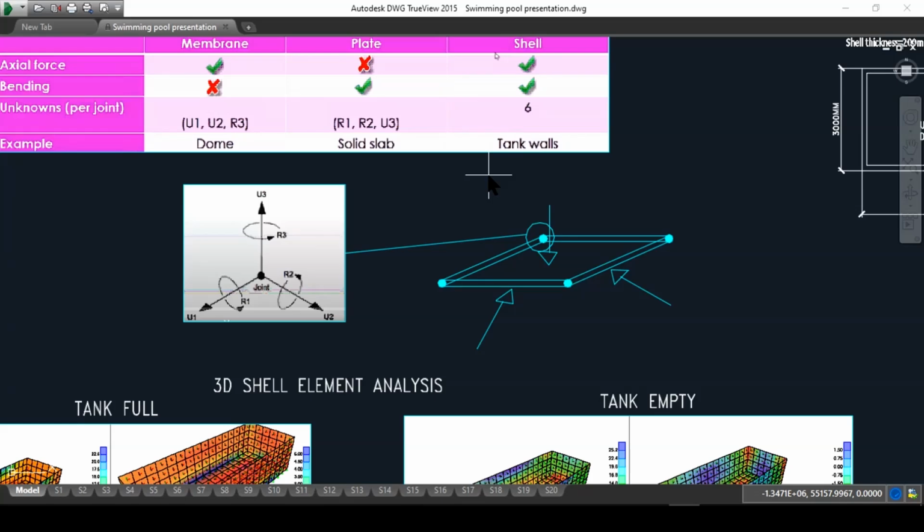And hypothetically, they say, okay, using a solid slab, a slab on beams, a slab on columns, that's probably the case. You will not get a rotation around the U3. Unless, of course, we consider a slab on ground and the ground moves in 3 dimensions, and then we assign the soil springs with shear couplers, and then we have shear deformation, and then we'll get movements in all directions. Yes, that's a different story.